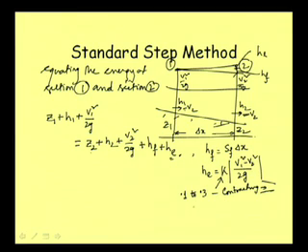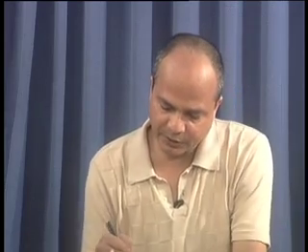And then it is 0.2 to 0.5 for an expanding channel, when the channel is expanding like that. That means it is clear that this eddy loss will be more when a channel is expanding rather than contracting. That part is very obvious from these values, and this point we need to take care of.